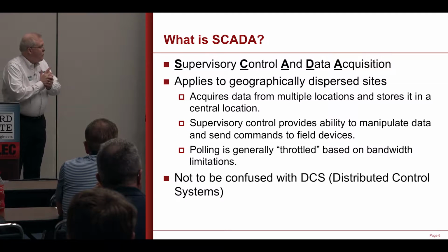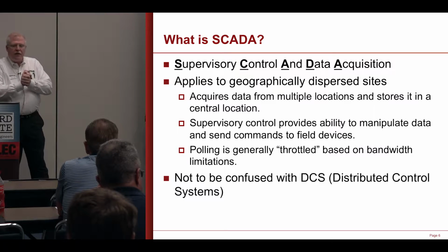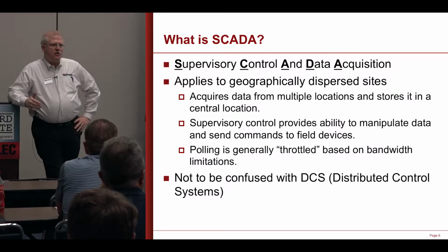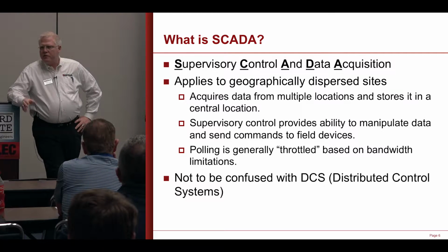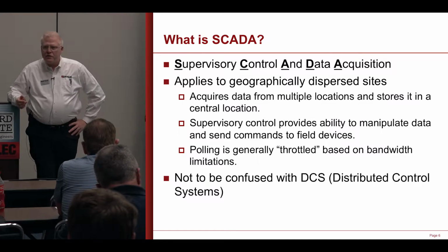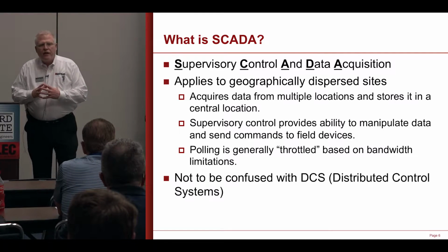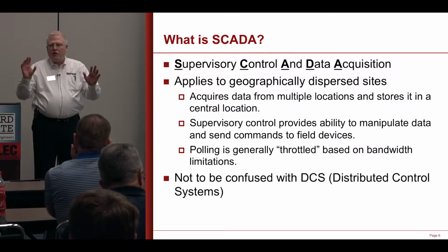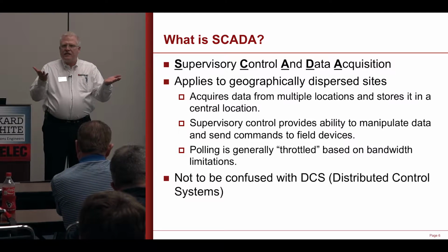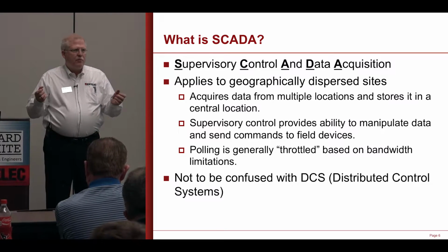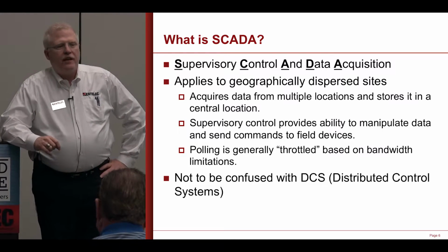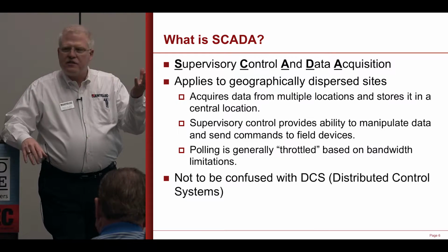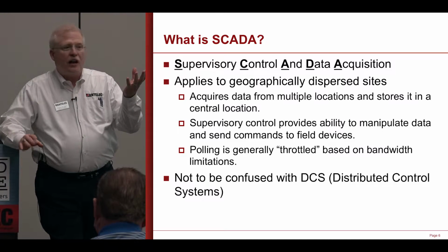All right, so the other thing about SCADA versus, anybody heard the term DCS, Distributed Control System? DCSs are what you find in plants, refineries, petrochemical facilities, fractionators. Those tend to run DCSs. If I look at a DCS and underneath how I set it up and configure it, DCS and SCADA look a lot alike, but they're different in a very fundamental way. In a DCS system, the communications between the host and all the field devices is critical. And if I lose communications, I lose control.